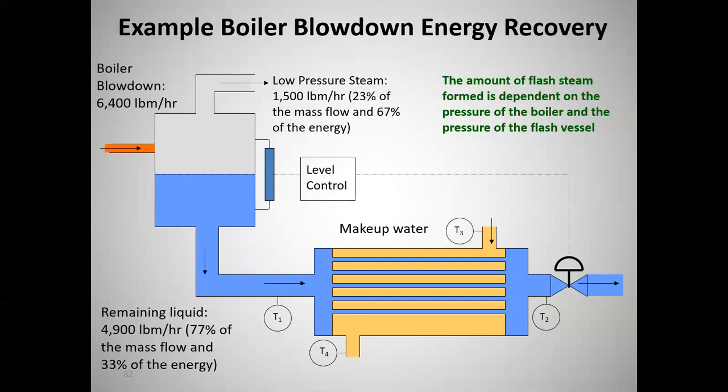And that shows up on a slide here in a few minutes. But this heat exchanger has got to be selected carefully. Plate and frame, where you take them apart with the gaskets and you can scrub them, or a single pass where you can open up the end caps and rod out the tubes, where you quickly and easily clean it. Absolutely. That's a great point.